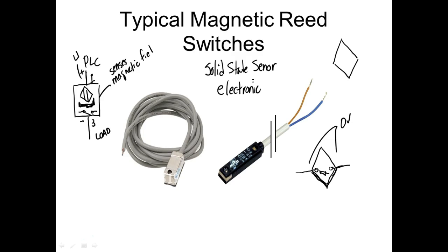That makes sense. It's not mechanical, it's electronic. And a solid state device can never drop 0 volts because it's a semiconductor. If you see a solid state device drop 0 volts, you might have to take the thing out and throw it away because it's shorted. I should say it will never drop 0 volts if it's not bad. And that's the way we can determine if the solid state device is shorted. If it drops 0 volts across those simulated contacts, then we know it's bad, right?